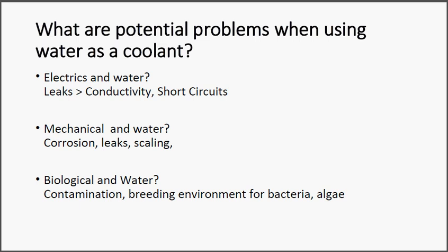And then we've got another problem. We've got rubber hoses and things like that in our car engine. If we move away from water and use something like 100% antifreeze, the problem is that the chemicals will attack the rubber hoses in your car engine. So what's recommended is to go for the appropriate mix, which depending on the manufacturer could be a quarter of antifreeze and three quarters of water, or half and half, and obviously depending on where you are and what you would need.